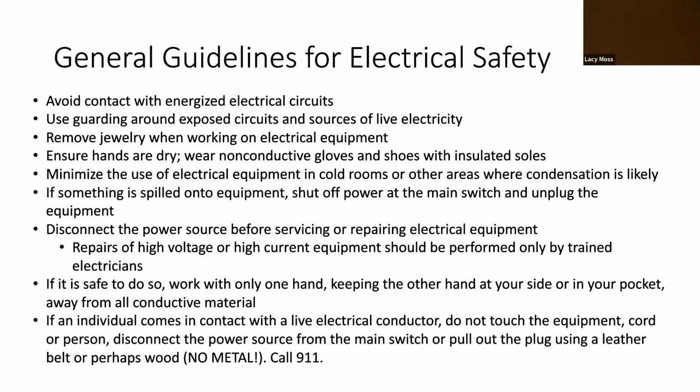If an individual comes in contact with a live electrical conductor, don't touch the equipment, cord, or person, because the person is now part of the circuit. So do not touch them if they are currently being electrified. Disconnect the power source from the main switch, pull out the plug using a leather belt or perhaps wood. I'd be amazed if you had a leather belt, much less wood, but try your best. Nothing metal, and then call 911.